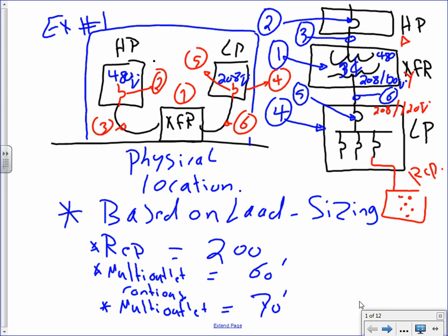Typically, guys, if you have a commercial industrial building with 480/277, lights and equipment will all be burning at 277 and 480, and the only thing that you will be burning at 120 is receptacles, right? Any comments, guys, on why this is so important in any commercial industrial building that you enter? When we went to Boston Scientific, did you guys see the transformer? Joe, you and I were looking at it, right? There was a big transformer on the floor, feeding another panel. That's exactly how you size this system, and that's exactly what we're doing. Any comments, any questions about what we're trying to achieve?